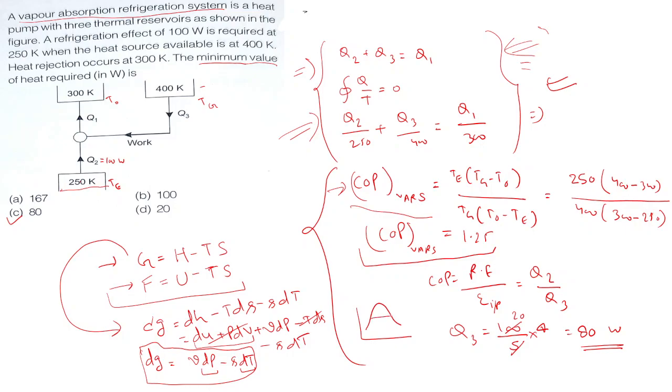Let's suppose this is constant pressure. So they say temperature is constant and pressure. So here phase change is happening, right? This is P is equal to constant, and for the phase change temperature is also constant, right? Both are constant. So at the phase change, what will happen with dg? dp is 0, dt is 0, so dg will become 0, right?